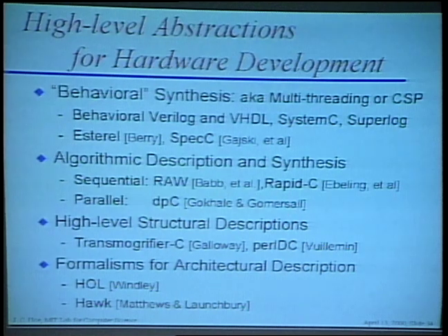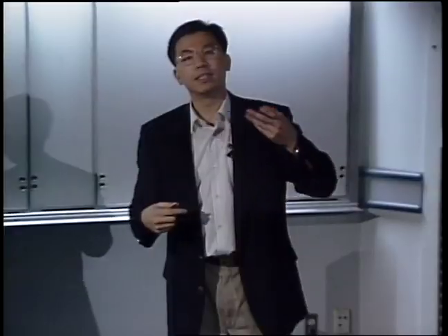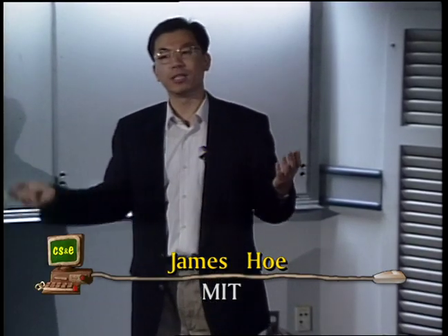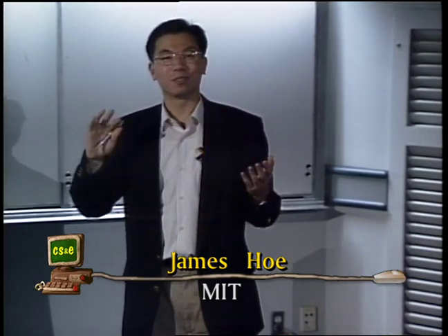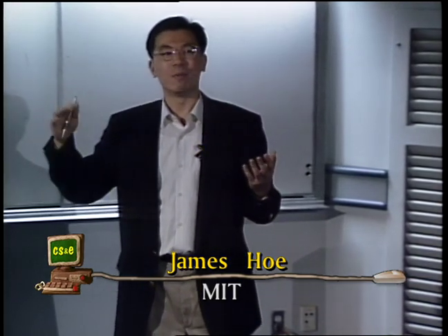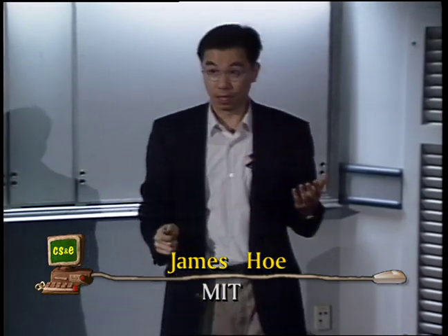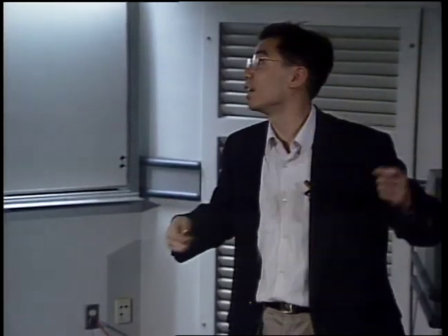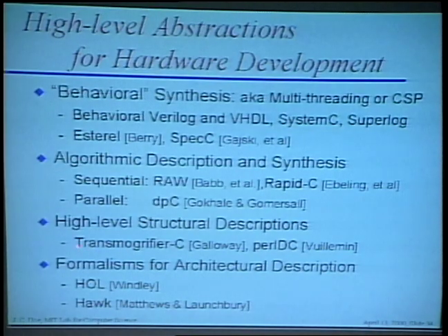And then you have this next category where people are leveraging the familiar syntax of C or C++, but they're also reassigning RTL-specific semantics to those constructs. And so essentially they're describing RTL with a high-level syntax. And the difference between this category and that category is that typically you take a description in this category, compile it using the software compiler, and you don't end up with a meaningful program.